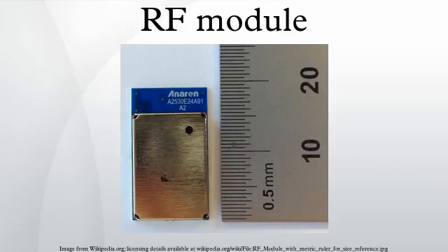Super-heterodyne receivers have a performance advantage over super-regenerative. They offer increased accuracy and stability over a large voltage and temperature range. This stability comes from a fixed crystal design which in turn leads to a comparatively more expensive product.